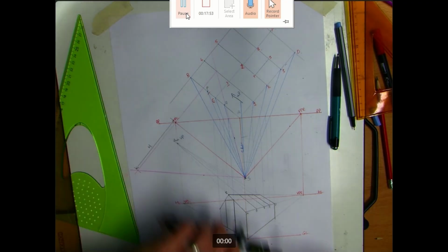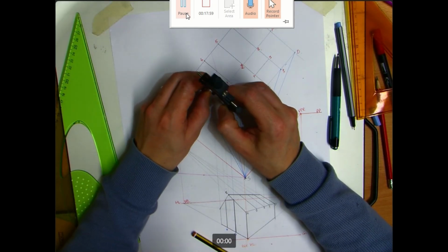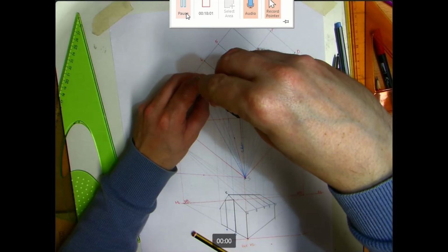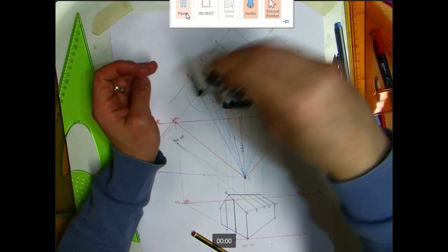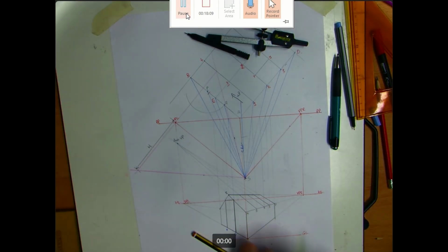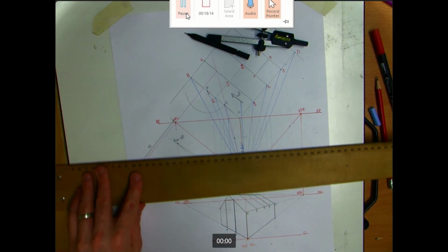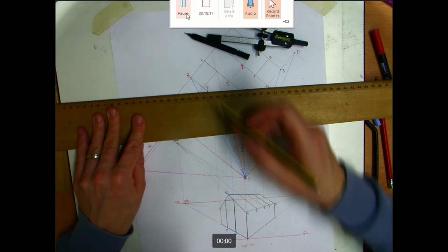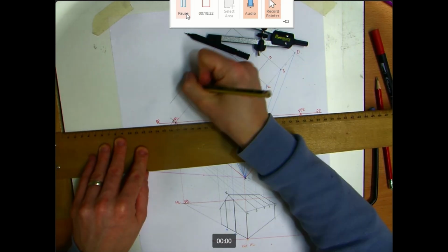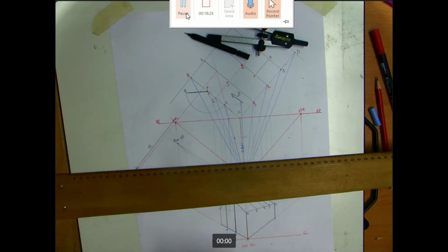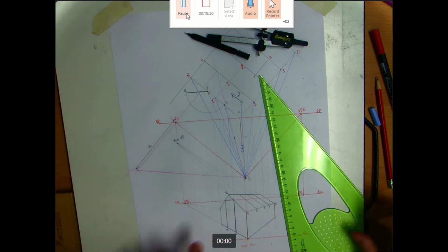Now, we're going to the next part, which is the door. And part B here of the door is the hinges at P. It's going to open up from a closed position. It's going to open up till it gets parallel with the picture plane. So we're going to rotate this open until it becomes in a parallel position with the picture plane. Picture plane I have set up to my set square, or to my T-square to be horizontal. So it'll open up to a horizontal position. Q is now positioned here. Okay, and we're going to then find that in our plan view.